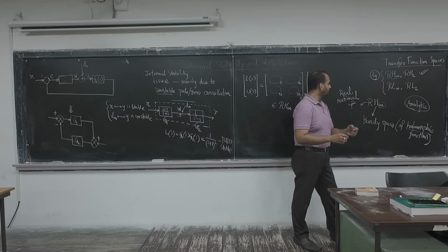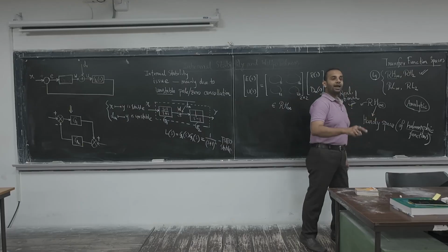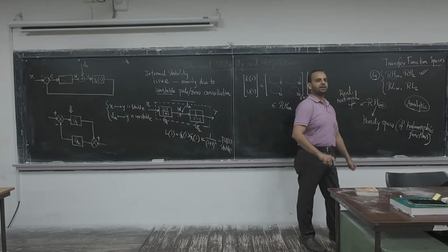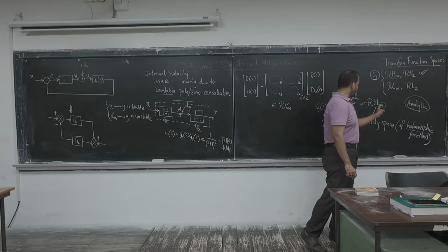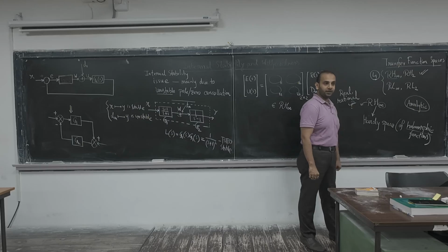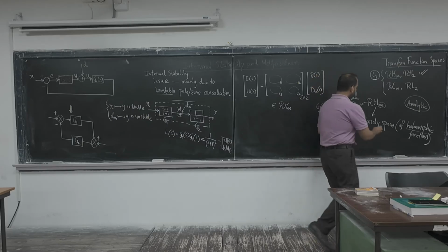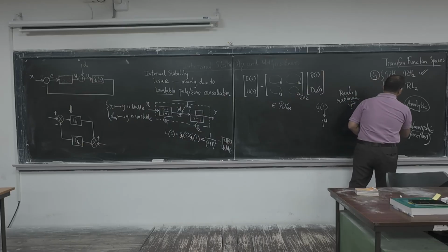W1, W2 are like real-time signals. It will be in H infinity, and these factors, say for example, (I plus G1 D2) whole inverse, and here (I plus G1 D2) whole inverse. These are the gains provided by these two transfer function elements. Now we have to check whether they exist or not. Right? Can you comment about that?